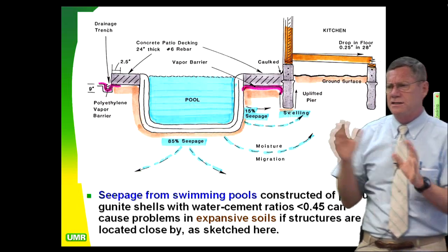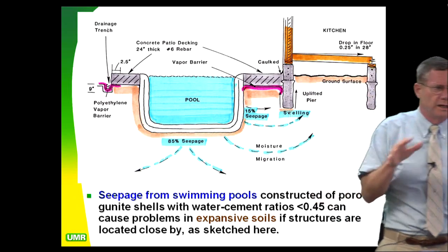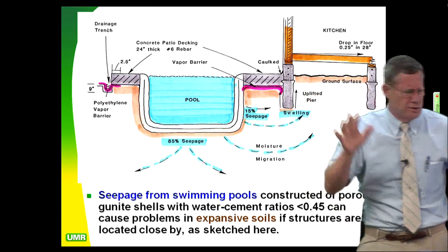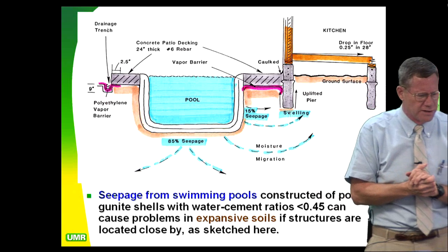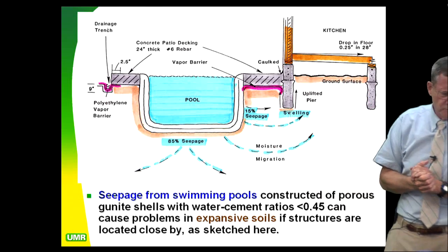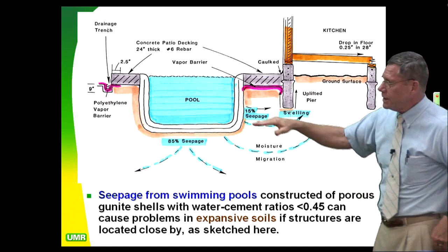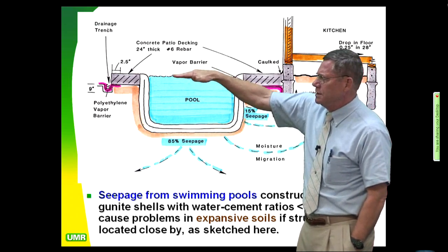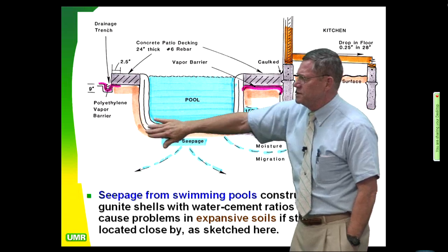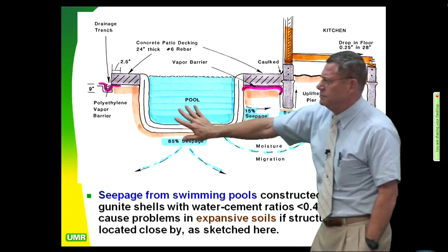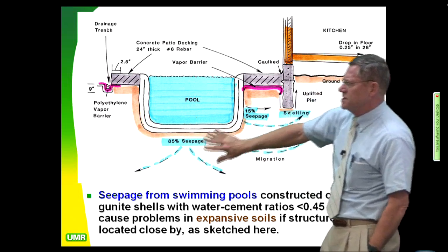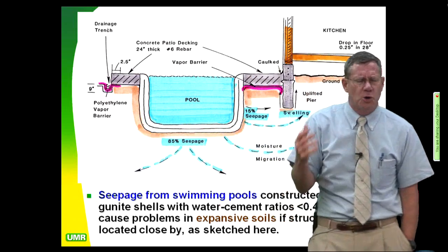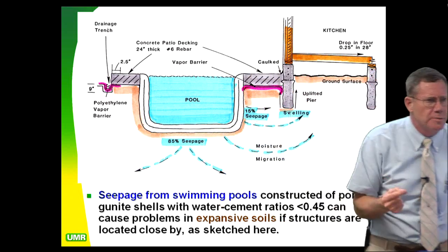And he insisted that State Farm get somebody with a PhD to come in here and see what's going on. And he was suing the soil engineer and suing the contractor and suing all these different people. And what you have here is you have more hydraulic head in the middle of the pool. So 85% of the seepage is right here. It's out the bottom. So it's going to go down, and this is partially saturated down here. So it's going to go down and be chemically adsorbed, with a D, adsorbed.